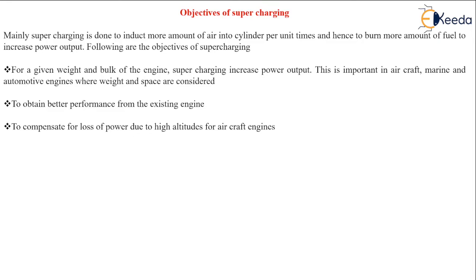In summary, the following are the objectives of supercharging. For a given weight and bulk of the engine, that is by keeping the engine the same, keeping the cubic capacity, the volume of the combustion chamber, the same, supercharging should increase the power output. As far as applications are concerned, this is an important factor in case of aircraft, marine and automotive engines, where weight and space are of prime importance.